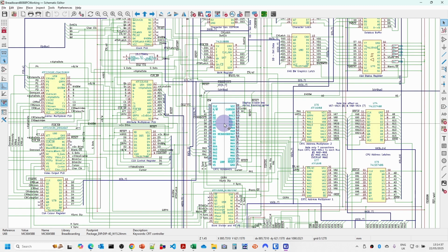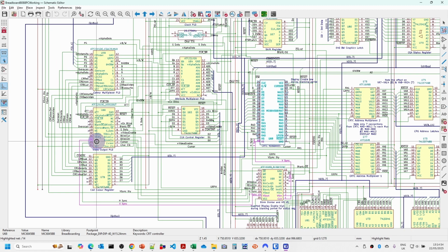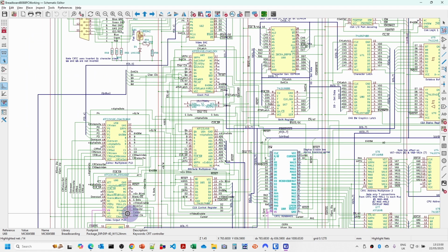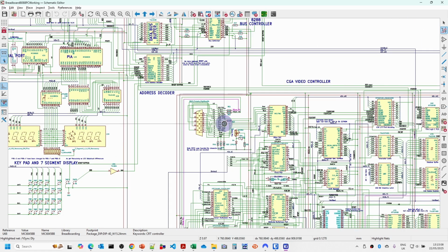We've got the cathode ray tube controller down here. And out of this, the horizontal sync and vertical sync actually go into here, and this is where it divides these down for the blink clock for the characters and the cursor. We also feed it into here and then comes out of here delayed up to the 15-pin VGA connector up here.